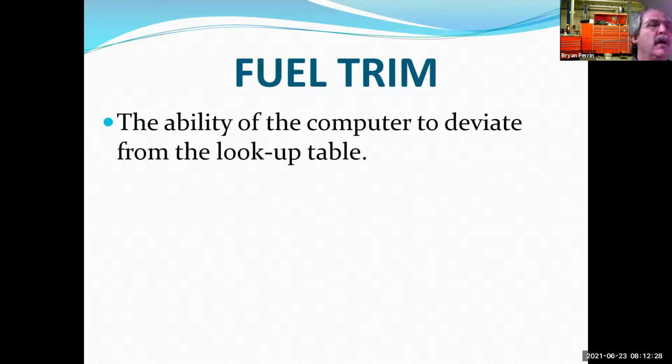We've done this. But if I'm chasing a car with a code that says P0171 fuel trim adaptation at lean limit, I'm looking for mass airflow sensors. I'm looking for vacuum leaks. I'm looking at all these things. Why is this car adding fuel? Why would it be running lean? Instead of stepping back going, why are we adding injector on time? Well, maybe there's a problem with the circuit where I have to hold it open longer just to keep it open the original amount of time, because of resistance in the circuit or resistance in the injector, things like that.